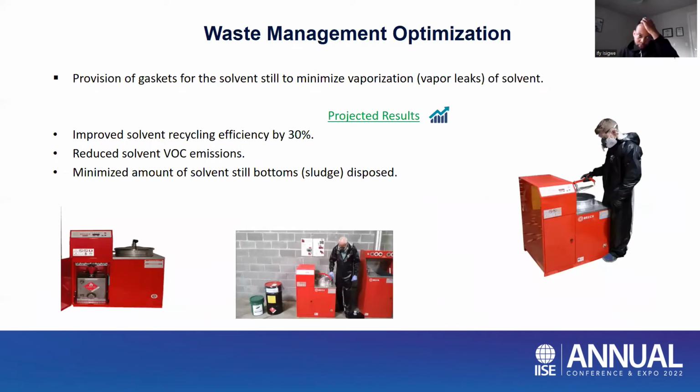Another thing we did was on the waste management side. Whenever they are running a solvent distillation still, we made sure that they implemented a latch, and also a gasket, to make sure that any vaporization that occurs is minimized. Thereby, you don't have any vapor leaks from your solvents that would be really harmful to employee health.